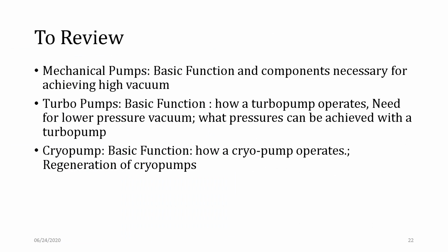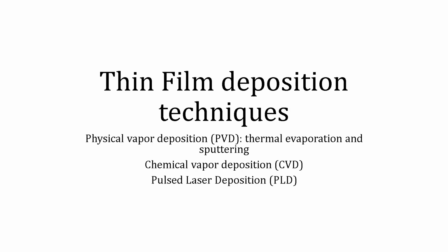So to review, we just looked at different kinds of pumps. Why should pumps be used? Pumps are very important to perform deposition. All kinds of equipment need vacuum pumps. We saw the mechanical pump, turbo pump, and cryo pump. And then comes the deposition techniques, the thin film deposition techniques.